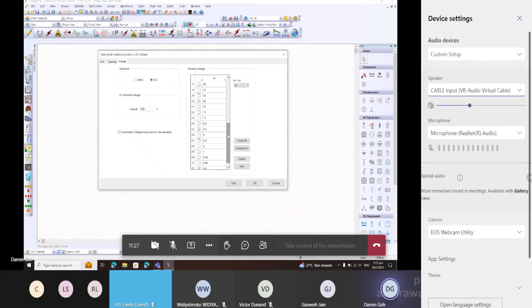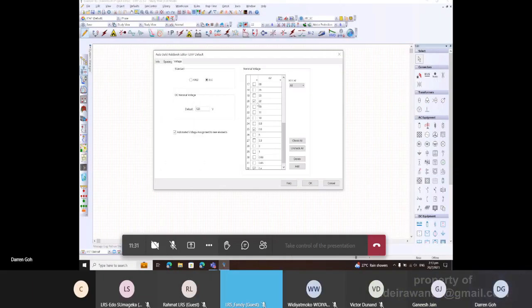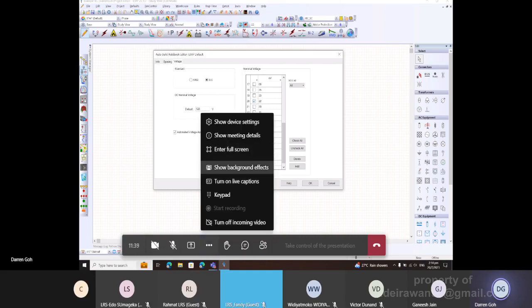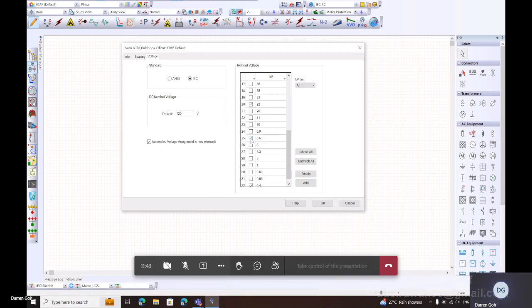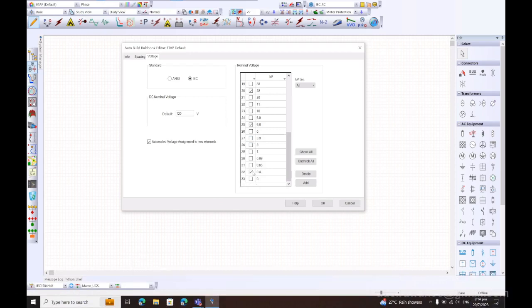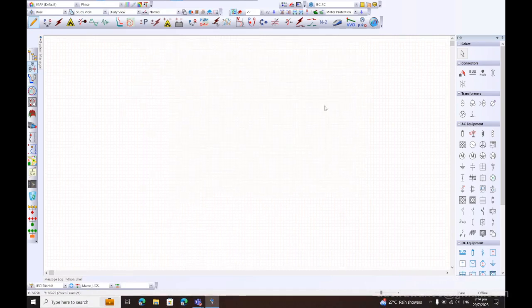According to the standards. Now in these examples, I'm going to use just 3 voltages. If you look at what I have selected, I'm using 22 kV as a distribution level. And then say it goes down to 6.6, assuming I have some medium voltage motors connected to it. And then further down to the LV system. So once I click OK, I can start the modeling.